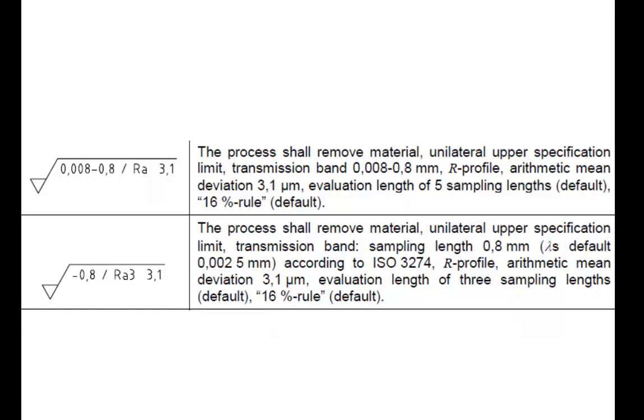Along only one path, at the place of the surface selected randomly, if the measured value is less than 70% of the roughness value shown on the technical drawing, then say that the surface is of good quality as it is specified by the designer.